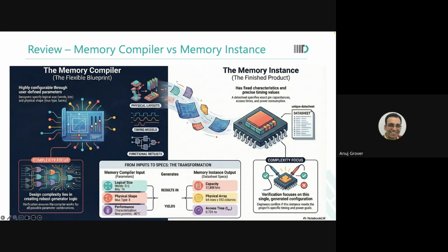At another place, let us say Shubham is the manager. And Shubham says, see, finally, when you build the global clock tree network, the inverters and buffers see 200 femtofarads of load. I have to drive 200 femtofarads. So he characterizes inverters on that.